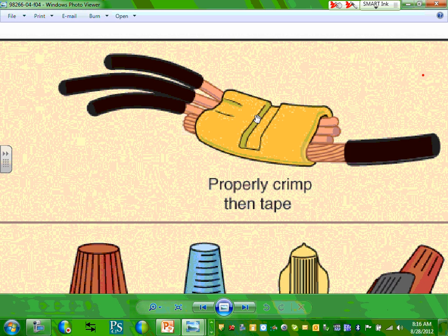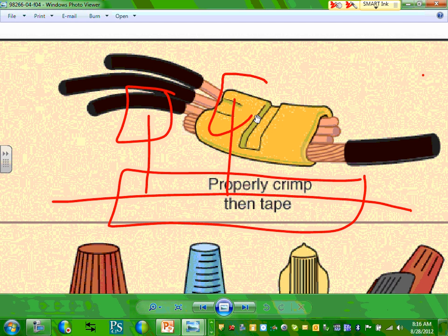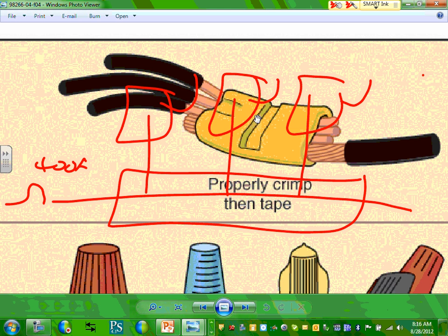What's the good thing about the taps with these is it's a cheaper installation. You have a gutter, you grab a gutter like this, and you tap a conductor, you bring a conductor here, and you tap and you disconnect here, disconnect here, disconnect here. Look at that, and here's your 400 amp coming in here, and each one of these disconnects is 100 amp, 100 amp, 100 amp. How do you do this installation inside the gutter? That's where you use this one. You tap it right here. Each phase, of course. That's where these become really handy.